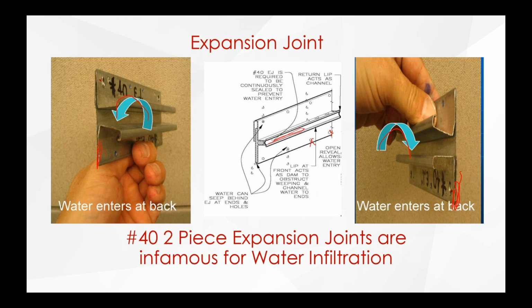So again, running the pencil test, you want to look at that. You want to make sure water is always free to get out, because if you put an acrylic finish over the top of this right here, you're going to seal that up pretty good, and it's going to be slow to get out.